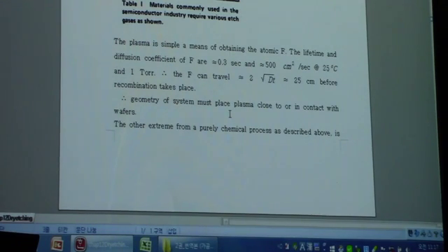In the wet etching case, the fluorine ions react with the silicon to form silicon tetrafluoride, which is a gas, so that you can see the bubbles coming out from the surface of the silicon wafer, for example. The same thing happens in the plasma chamber when the chemical process is involved.